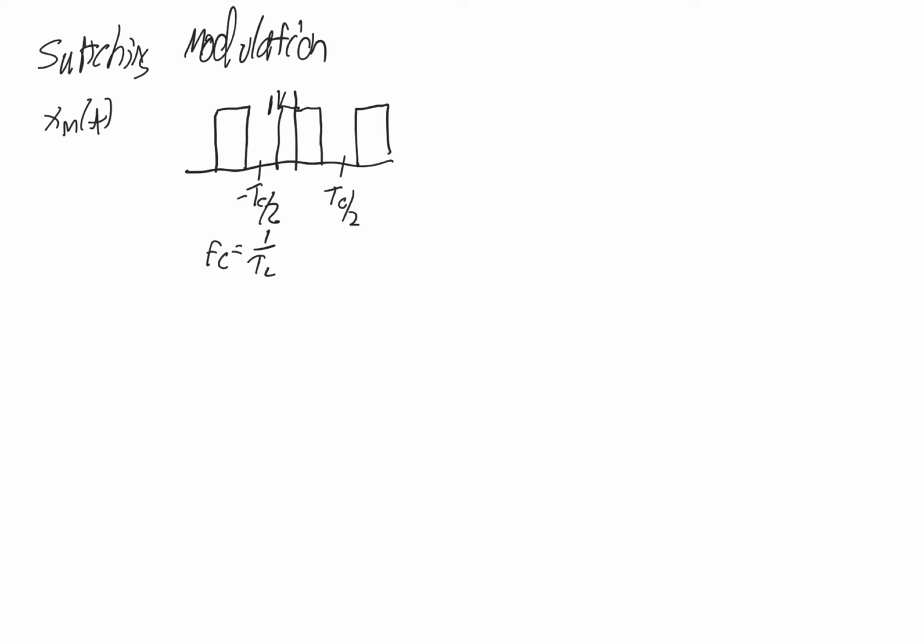If we go back to chapter 5 and look at table 5.4, this is a periodic signal, so it has a Fourier series. It has a DC offset, so we can see the average DC value. The DC value is half a volt, because half the time it's at 0 volts and half the time it's at 1 volt. We've drawn it here to be an even signal, so when I write this out, I'm only going to have cosines with no phase shift.